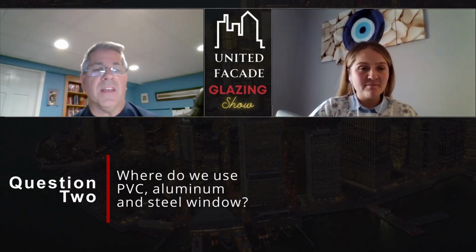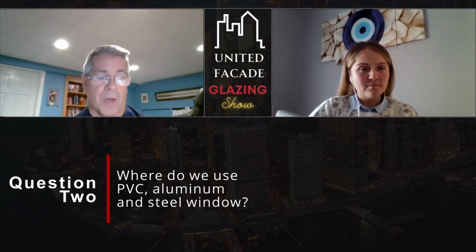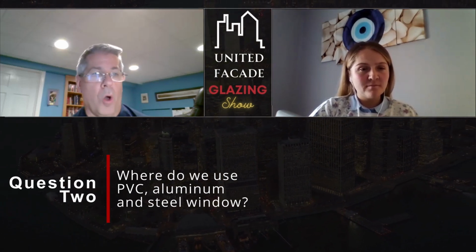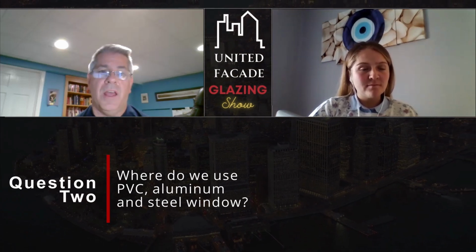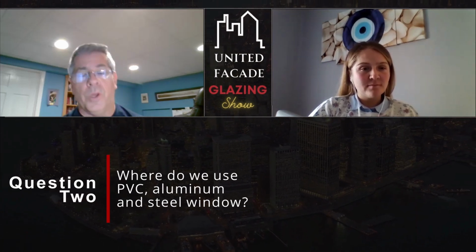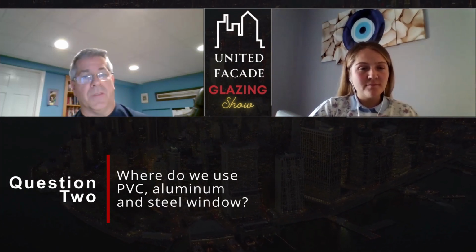If you did not have a thermal break between the exterior of the frame and the interior frame, the cold would just penetrate through the aluminum material from outside to inside, and condensation and frost would form on the inside face of your building because of the different temperatures.